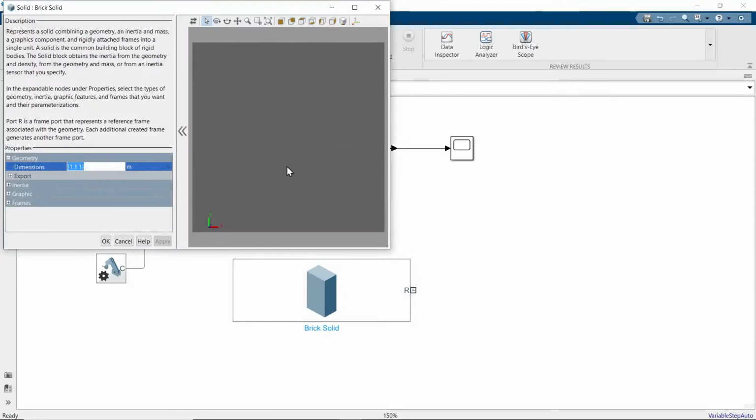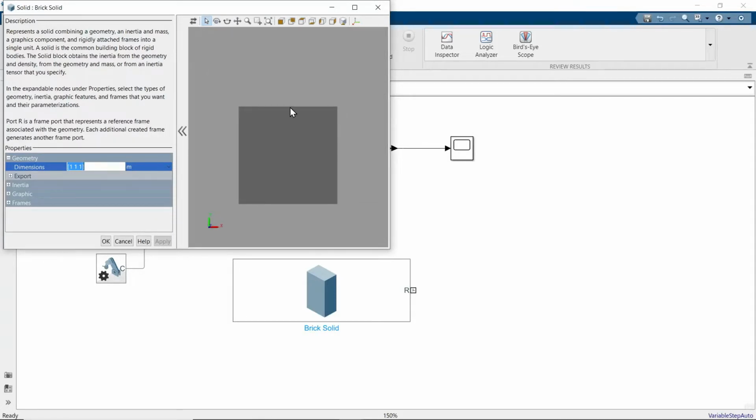So from the top view, we can imagine now that we need to make the x dimension 2.4 meters, because that's the dimension where the collar will slide back and forth, and it'll be sandwiched between the two springs in that dimension. So the y dimension doesn't matter, we can make it 0.3, and the z dimension we'll make it exactly 0.1 to match the height and width and length of the collar. The collar is going to be a perfect cube. So apply F5.